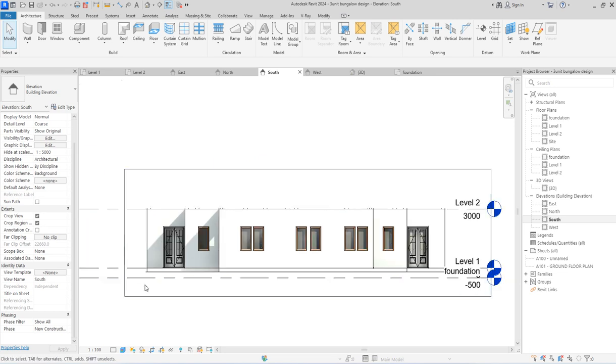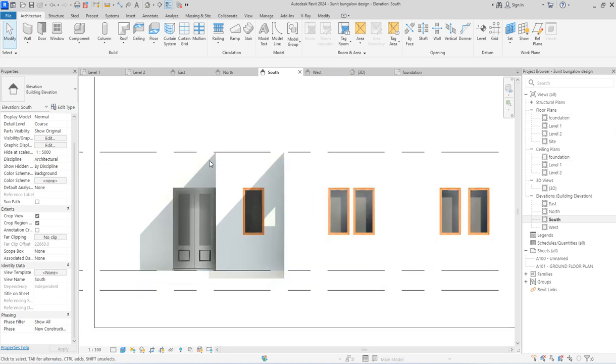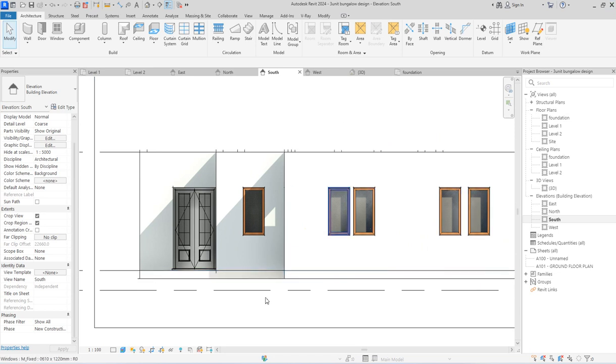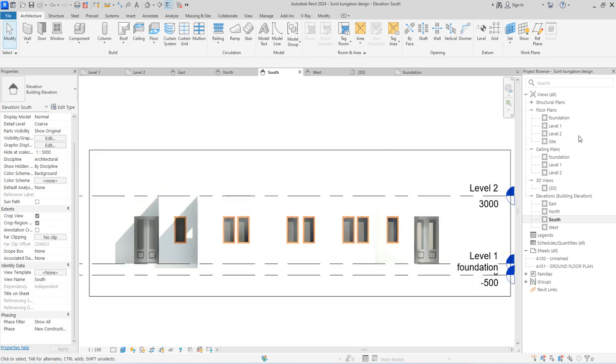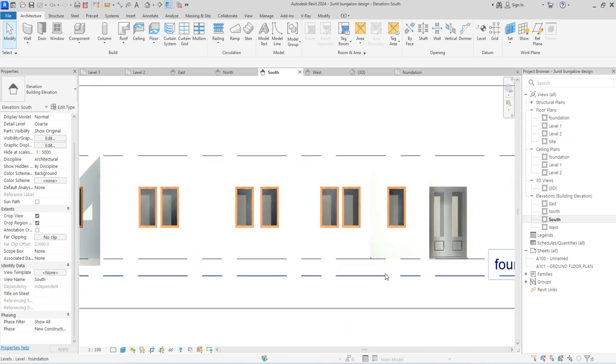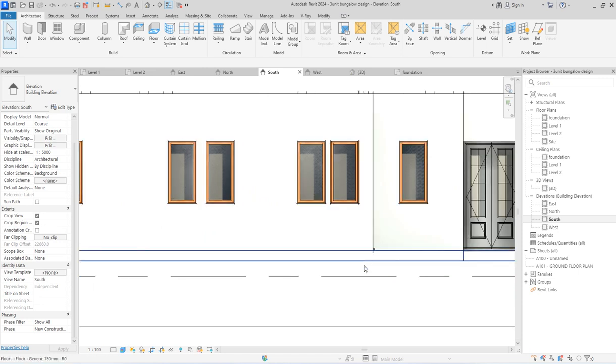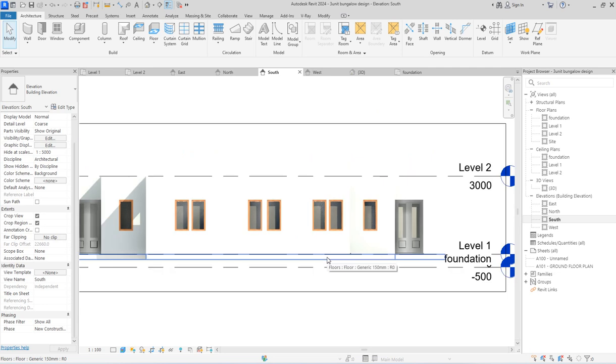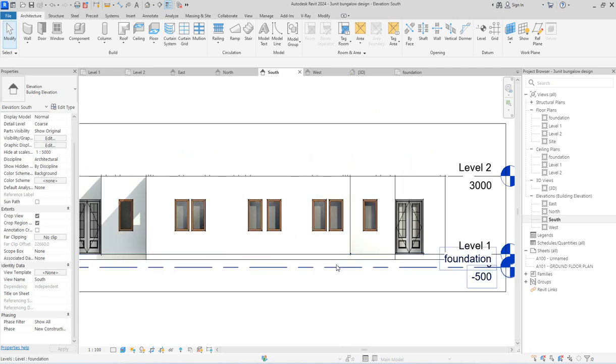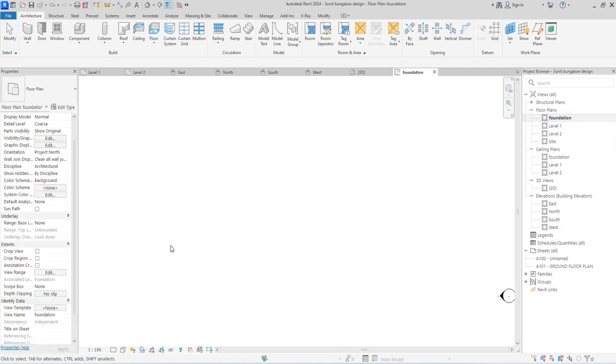So now that is what I did, and I want to go back there and paste what I have copied from the wall so that this wall will appear at the below level. So that is what I want to do now. The reason why I use 250 is because I don't want it to cut through this slab, because the slab still maintains its 200 mm thickness. So go back to the foundation and do the needful.